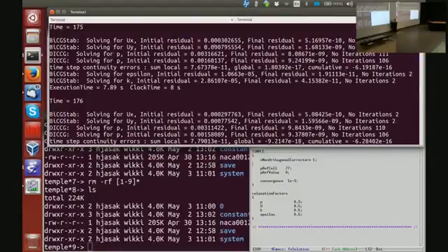So we go round and round in circles and keep solving them again until things stop changing. When your fields stop changing, your initial residual will drop below 10 to the minus 4 or 10 to the minus 5, depending on the definition. So the fact that the final residual is low does not mean that I have converged over the nonlinear terms.